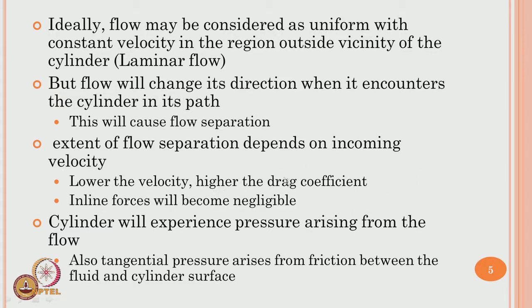Now, the drag coefficient, which is called CD, is a very important item, and it is now actively argued upon in the research front, which we call the drag crisis. I will talk about that slightly later in the next slide. So, when the drag coefficient is enhanced, inline forces will become negligible. Now, the cylinder will experience pressure which arises from this flow pattern, and therefore it also creates tangential pressure which arises from friction between the fluid medium and the cylinder surface.